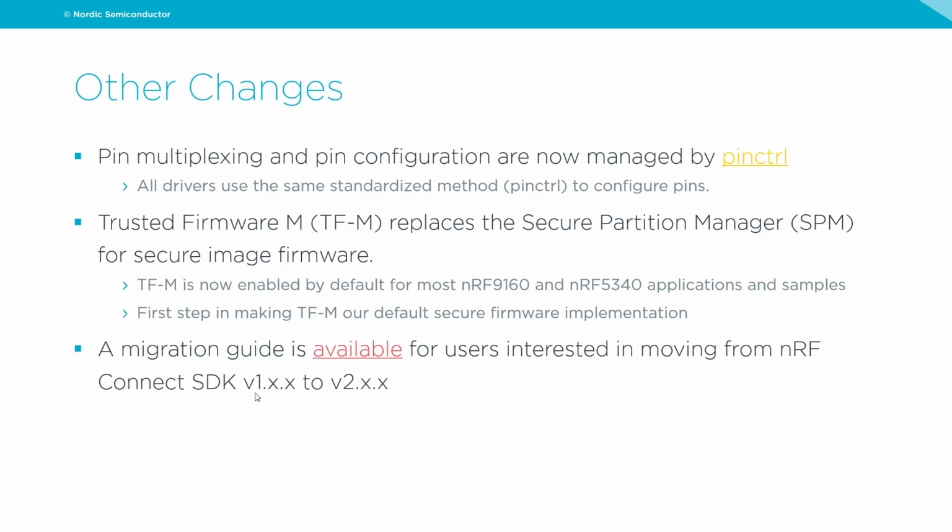As for other changes in the nRF Connect SDK version 2.0.0, pin multiplexing and pin configuration are now managed by the pin controller subsystem. This subsystem is actually inspired by the Linux kernel, and it offers great standardization and portability for all drivers that interact with pins. By all I mean the drivers that interact with pins to route their signals, like UART, I2C, and so on. So all of these drivers now use a standardized method to configure the pins, which is great for portability and standardization.